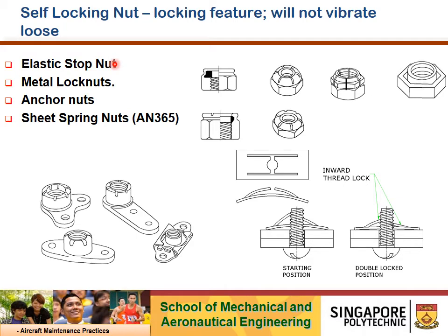Alright, and metal lock nuts are used in a high temperature environment. It is constructed with either the threads in the locking insert out of round with the load carrying section or with a saw cut insert.